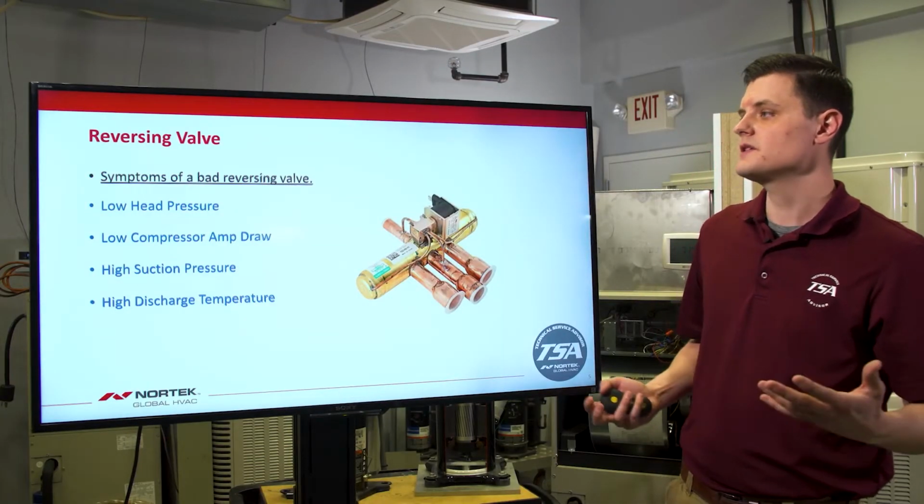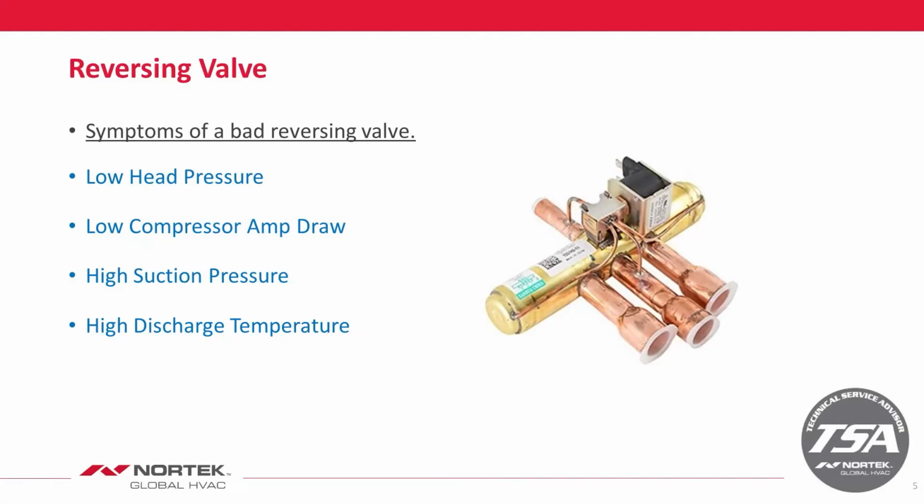Now, some symptoms of a bad reversing valve would be the following. These are a couple of things. One, you'll have low head pressure. Two, you'll have low compressor amp draw. Third, your suction pressure is going to be higher, and you'll also have high discharge pressure.